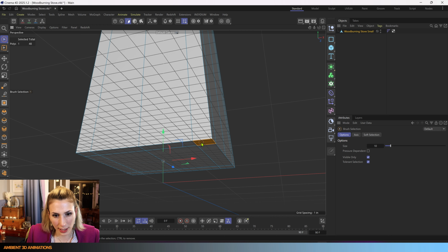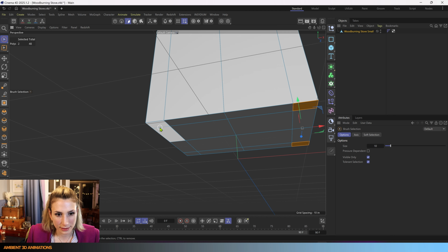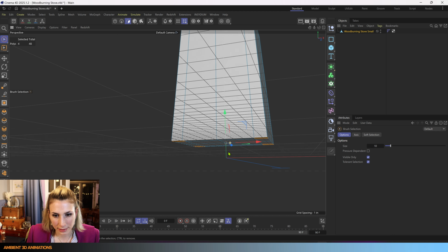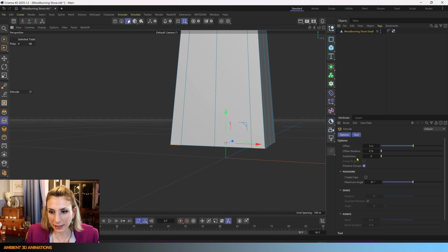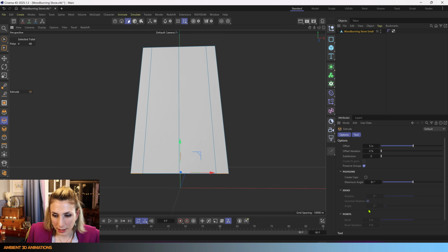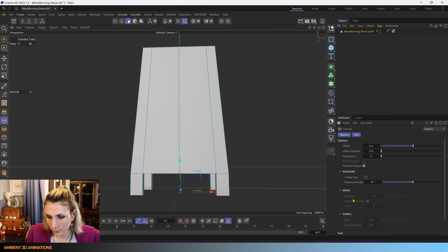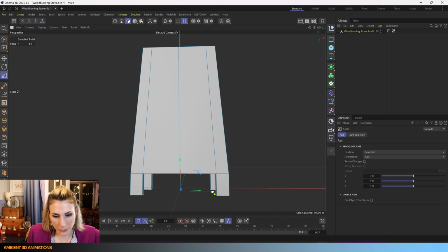And then we can go ahead and click on these 4 areas here and use the hotkey MT for the extrude. So now we're bringing up the extrude tool, and we can extrude this and hit apply. I'm going to use the T hotkey in order to scale these out a little bit.